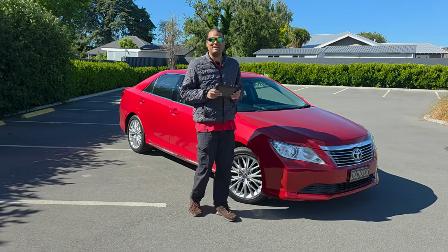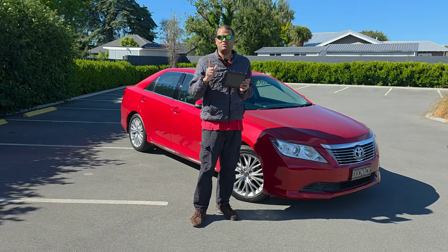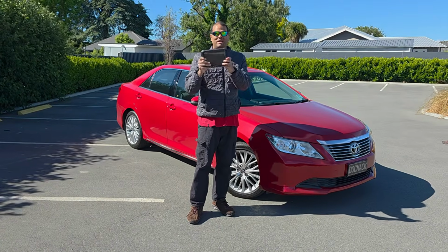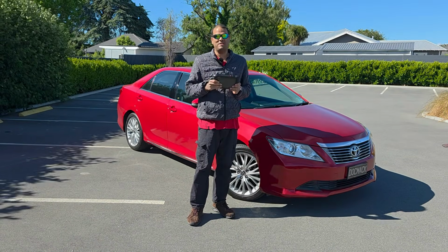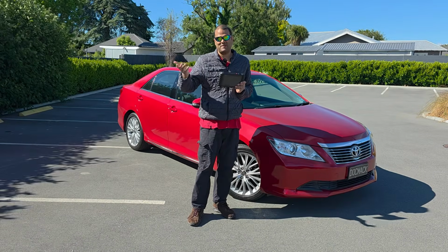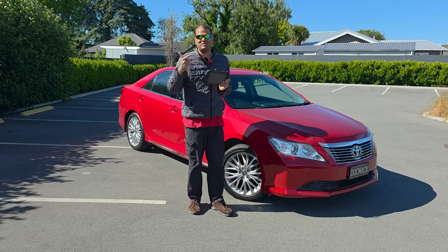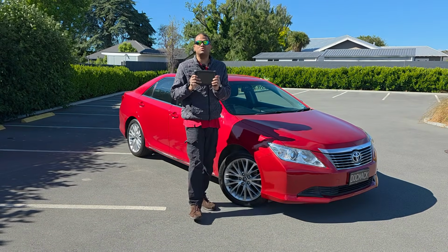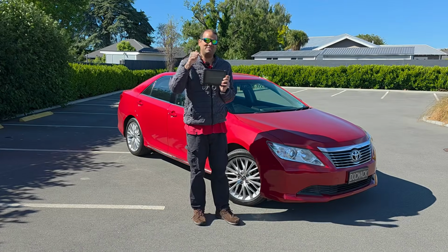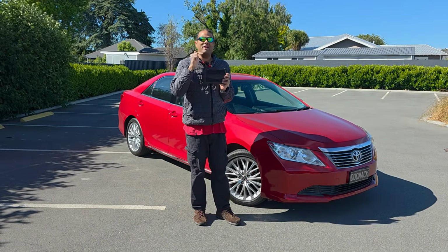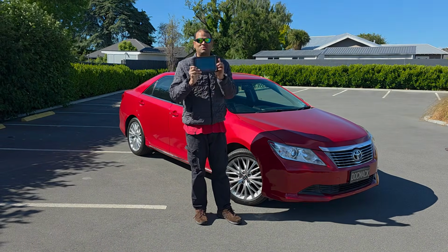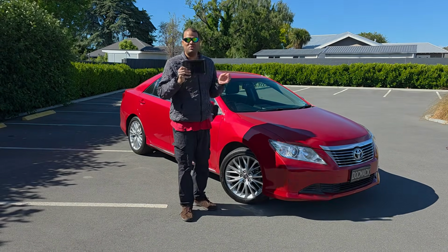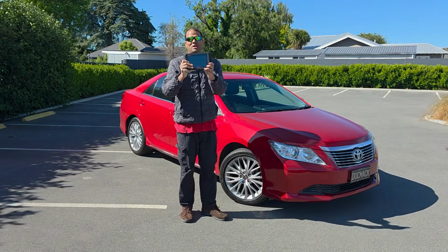Now there's something called live data, which is very useful when you come to diagnosing your vehicle. You can look at engine codes. Let's say, for example, you've got a P0301, it's a cylinder 1 misfire. However, those are either stored, current, or pending as well. With this one, I'm going to use what's called live data, which means exactly what's happening now, and that is what you need to use to diagnose your mass airflow sensor. So without further ado, I'm going to show you how to diagnose it using any scan tool which supports live data.